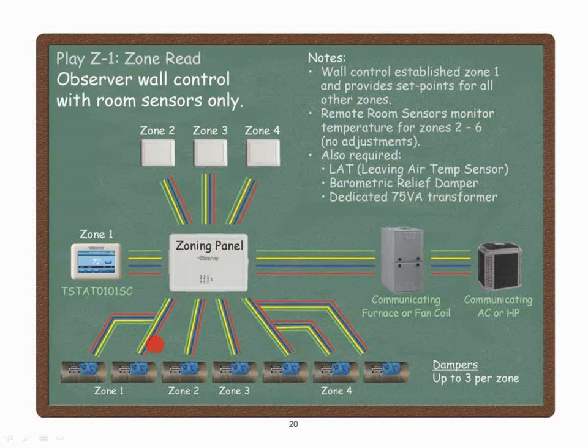And then the outputs to all the dampers, on our drawing here, we're showing it as 4-wire. In fact, it is only 3 wires that you need. There's a common wire, there's a power open wire, and a power closed wire. However, just to make everything easy and for our marketing folks to say everything is 4 wires, we show it that way on here, right? So if you just run 4 wires to every single thing possible, you're covered. But in reality, the zone dampers only need 3 wires.